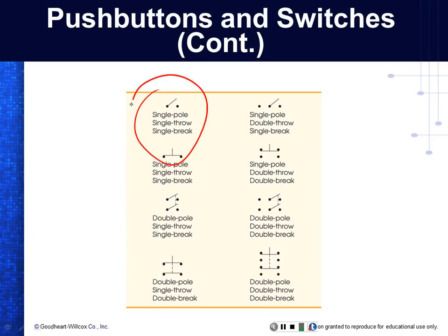So like here, if I close that one, it connects 2 lines, right? Well, on the other side, if I look at this one, I would have basically 3 lines. I may have one coming in here, one coming in here, one coming in here. So this could be like a selector switch. I could turn on this half over here, or I could turn on this half over here, depending on which way I throw the switch, but not both at the same time.